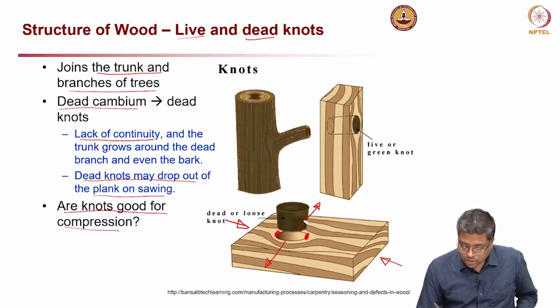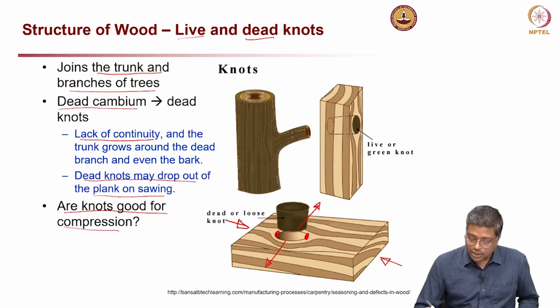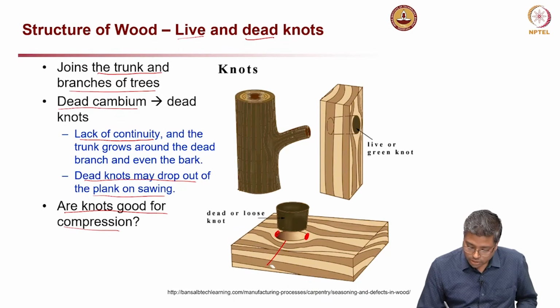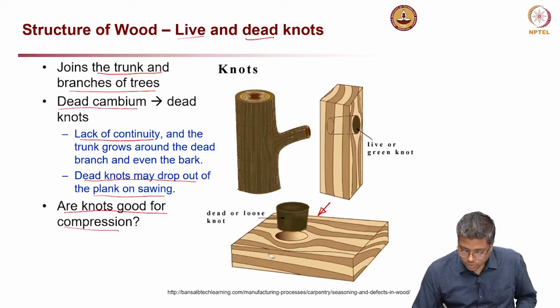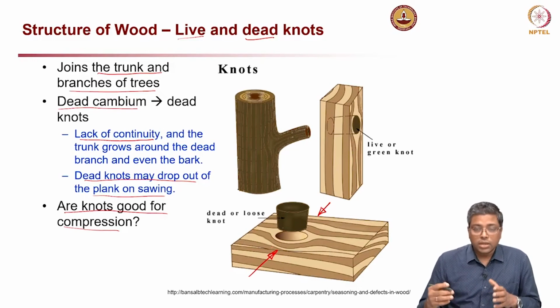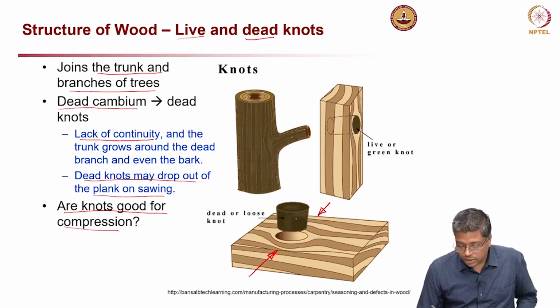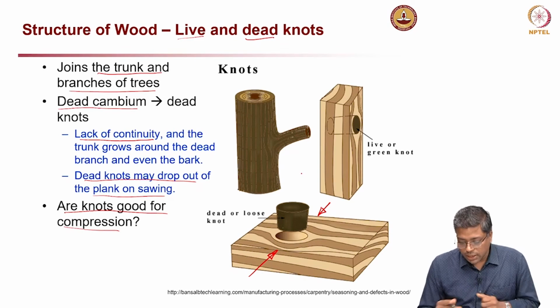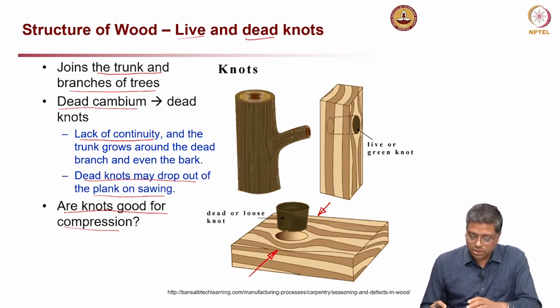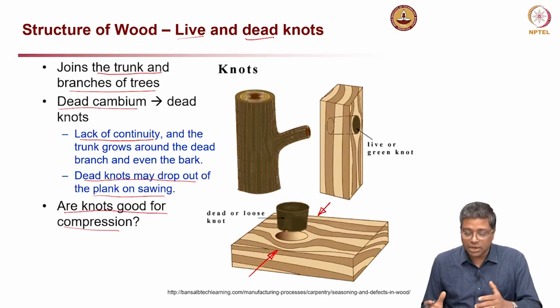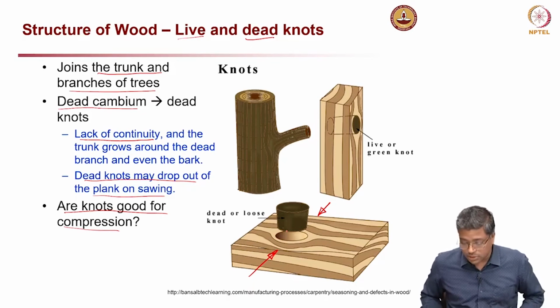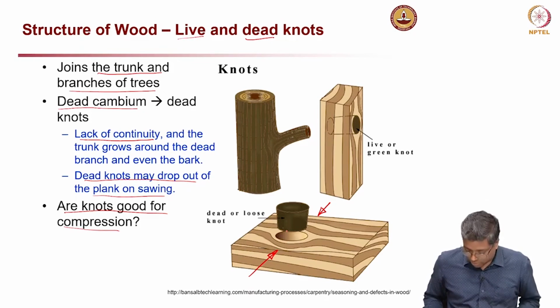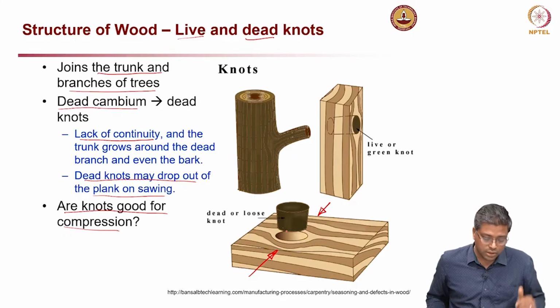That is one thing. Now, if I apply a load in the other direction, in this direction, then also there is a compression and it might push the knot out, and you might experience a stress concentration. But depending on the direction it might not affect much in this direction, while in the other direction which I showed you earlier, it will definitely have some impact on opening up or cracking of the wood along the grains or between the grains.